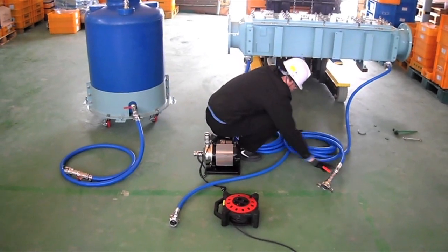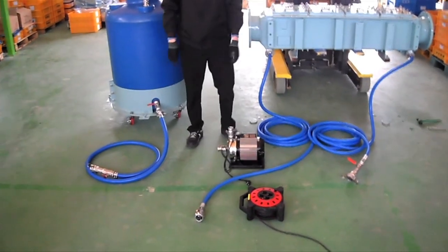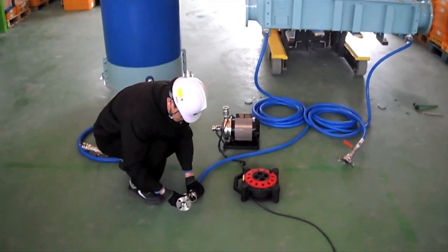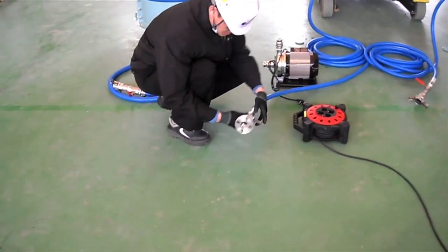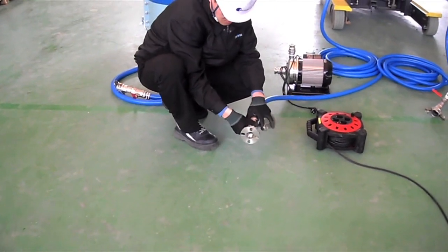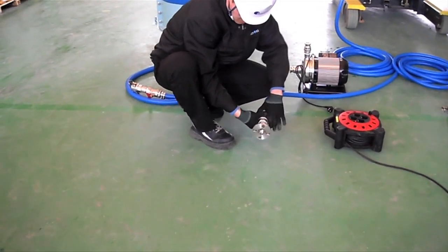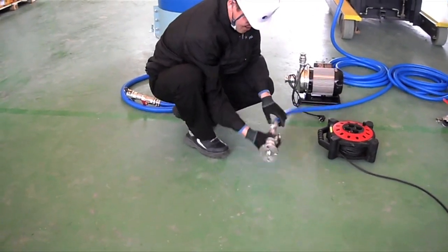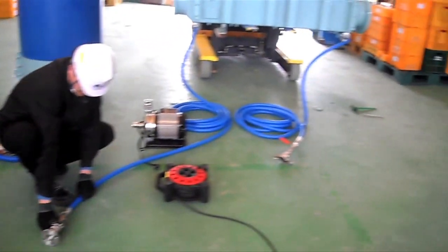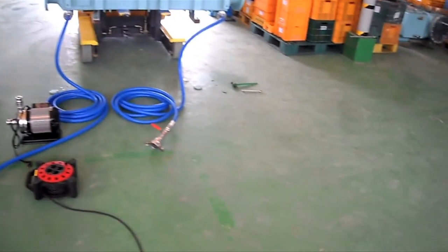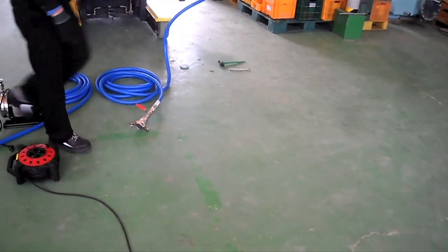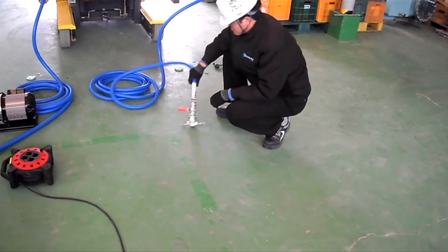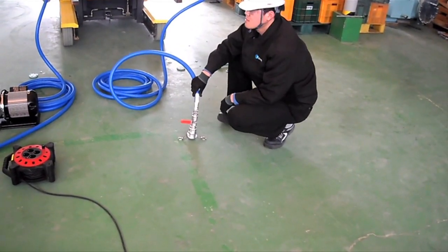3. Connect FW cooling service line of ship to coupling C4 of pipe AC3 using connector. 4. Connect coupling C3 of pipe AC2 to bilge holding tank pipe of ship using connector. Connector will be provided by the manufacturer. 5. Drain wastewater containing cleaning agent and open valves V3, V4 to clean inside of ECU.